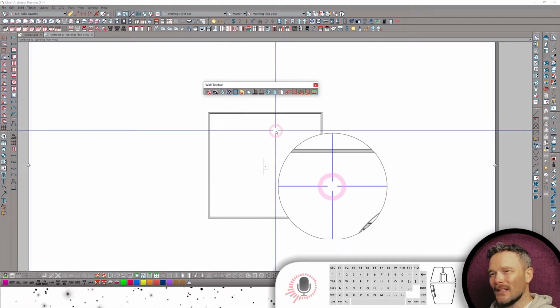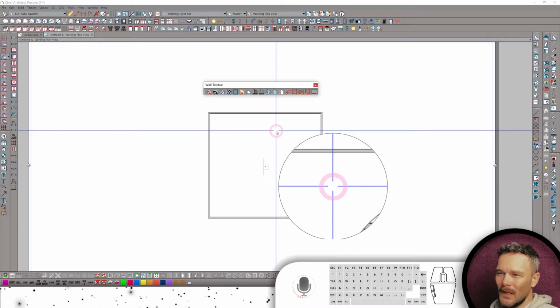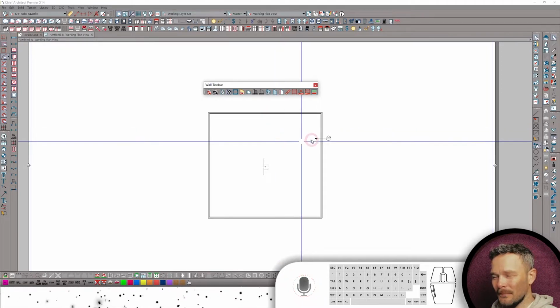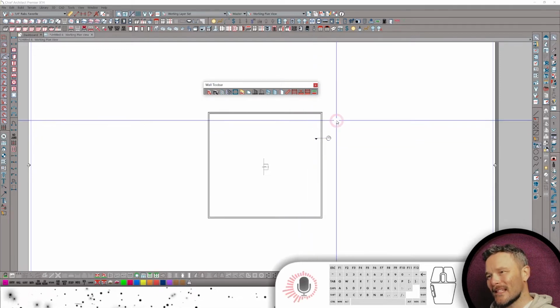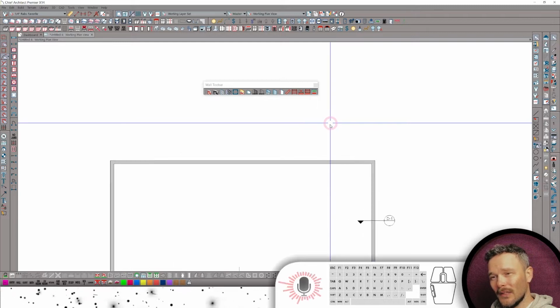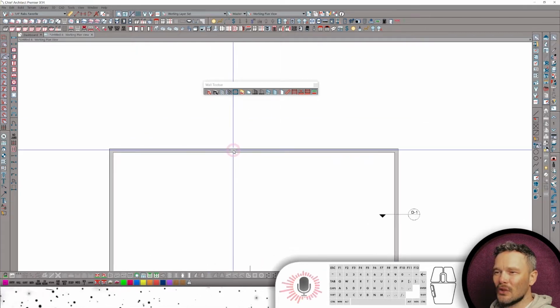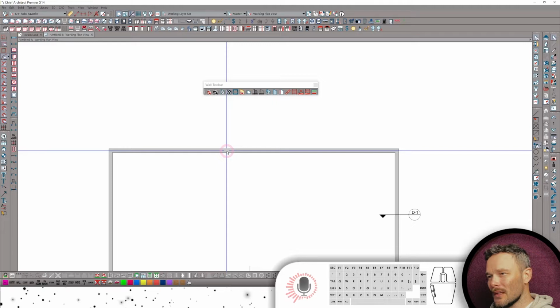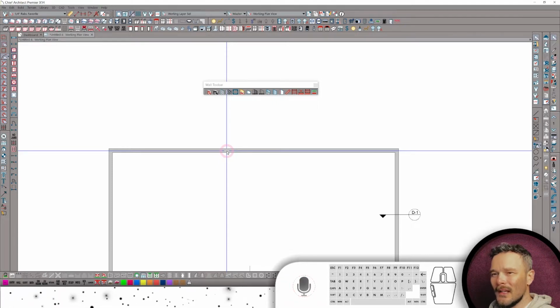Now, I won't get into how exactly these work. If you know how to use wall types at all, it should be pretty self-explanatory. Basically, the existing walls live on their own layer, new walls live on their own layer, and the fill style is driven by those. Now, you'll notice something about my particular walls is that I've got solid fill through and through.